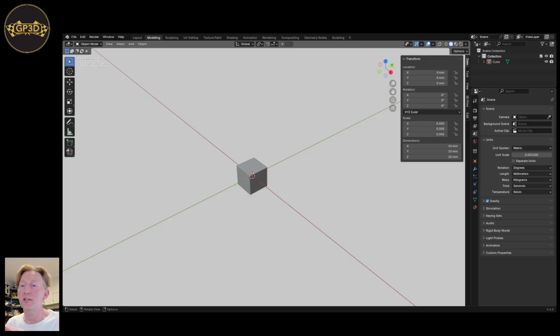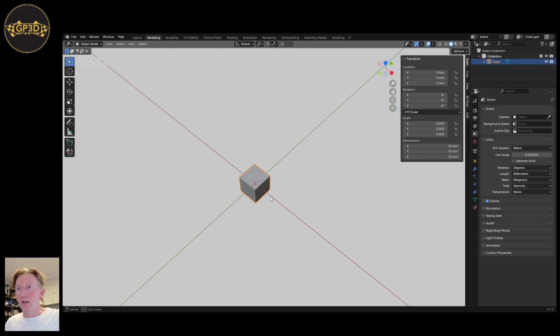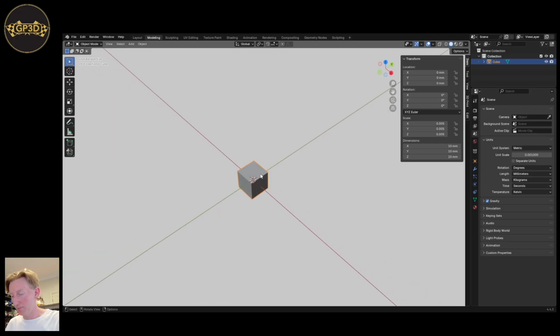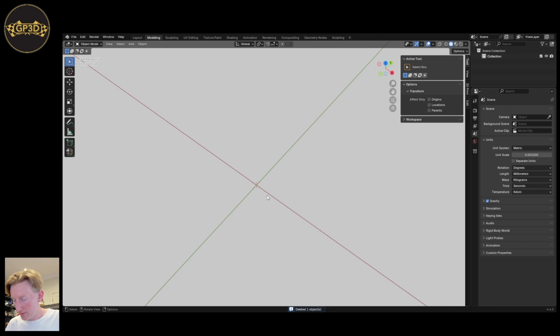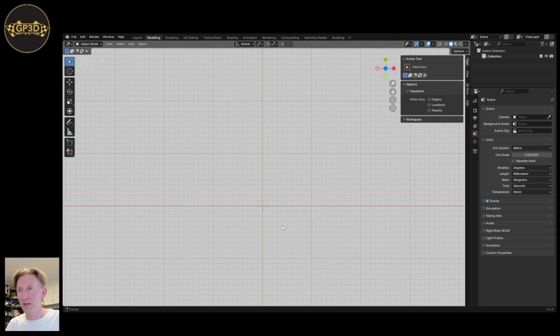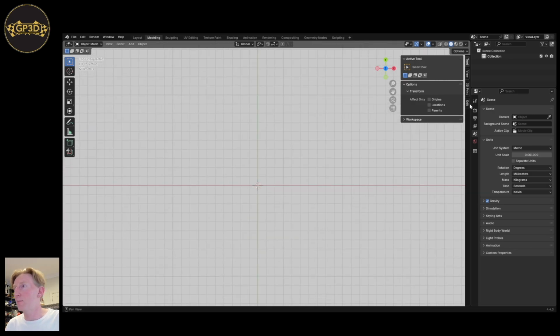And then it'll be mostly non-destructive with a little bit of destructive modeling of the objects. And that should get us from nothing, or a cube on the screen, to a shape that's going to represent and replicate this component. So what will I start with? I might actually start with some cylinders, so I'll delete that one. The number 7 on the keypad is a shortcut key that gives you the top view. So now I've got a top view, I can see my grid.